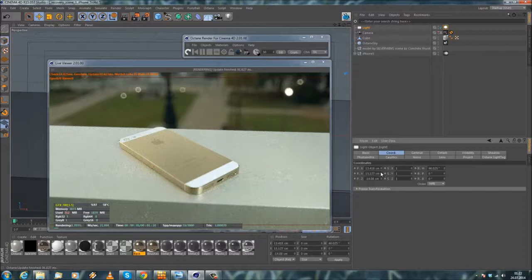So 15, 16 might be okay, but as you can see, the reflections are still there. If I turn off the area light right now, you can see here is a reflection, here is a reflection, which is pretty cool, and which only really works if this is also modeled perfectly. Because if all this stuff didn't have any edges and you just had a model where everything has 90-degree edges, you wouldn't get these reflections in your model, because the edges are just not there where the light can reflect, and this would really hurt the final rendering, you know.